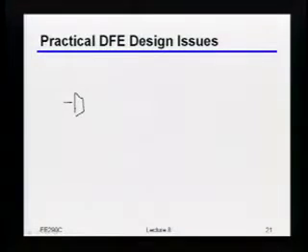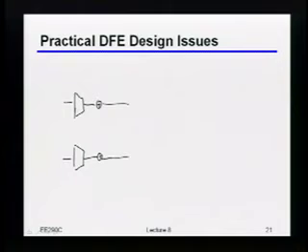So just to give you an idea of what that looks like, I just wanted to quickly draw what a two-way interleaved DFE design, sometimes called DDR, which just stands for double data rate, might look like, at least just for one tap. Okay? So if you did something like that, you might now have two independent summers.